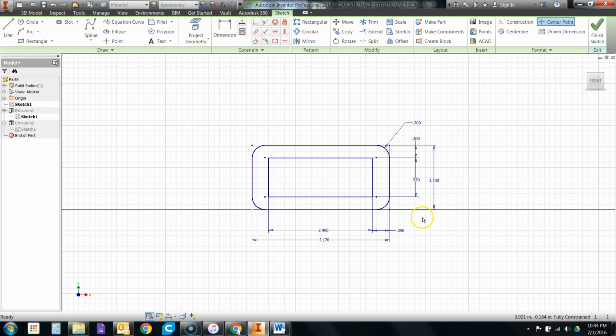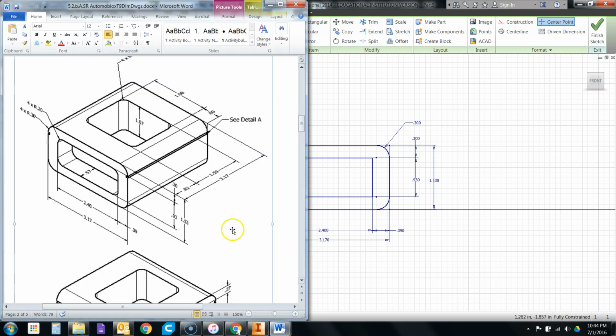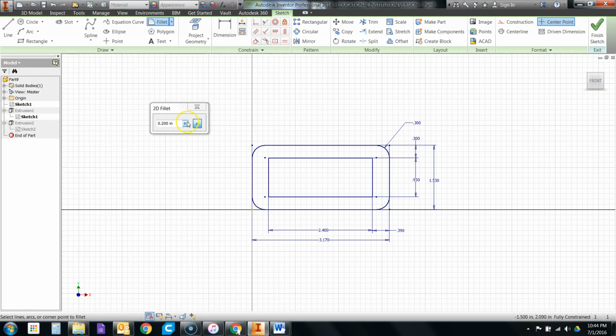And you don't need to do this, but I want to be able to point out dimensions to you very clearly. I also need to dimension the corners for their fillets, and remember that they are 0.2. I already have 0.2 selected. Corner for each one of these. And if it moves any of your dimensions, feel free to move them back if you want to. It's now done.